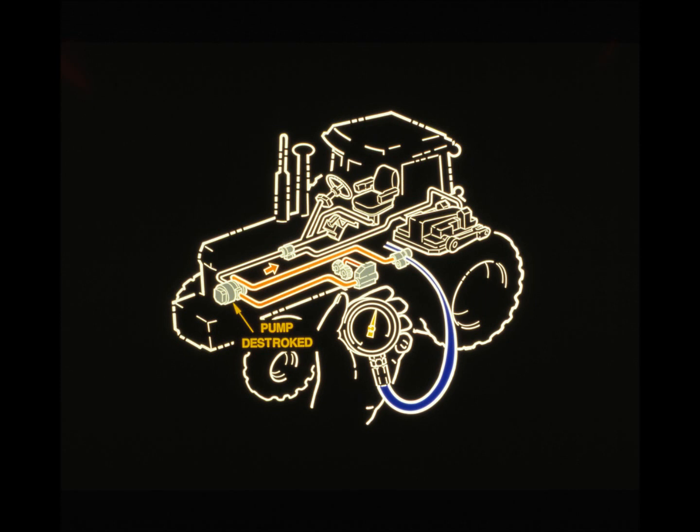Destroking the pump shuts off any flow of oil to the high-pressure system. Oil that was leaking to sump now flows to lube. Increased oil flow raises lube oil pressure substantially. If there is no high pressure to sump leak, lube oil pressure will not vary when the pump is put in and out of stroke.